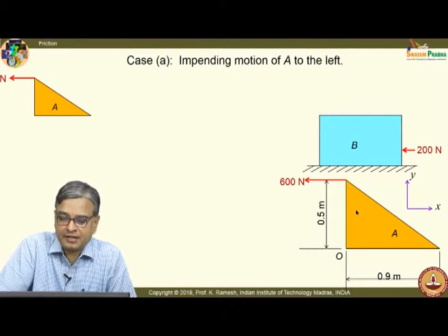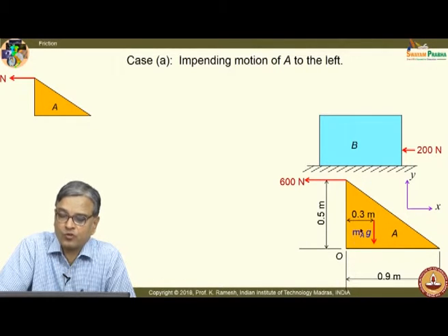So, I have the free body drawn here. I have to put the forces, and I have the weight acting like this. The question is, what is the value of MA we should find. And I would have in general a frictional force developed, and this direction of friction opposes the force of pulling. Okay. So, that is fine. And as we have discussed already, I would not put this normal reaction passing through the centroid. I would put it at an arbitrary position. Let that location be at a distance of d.